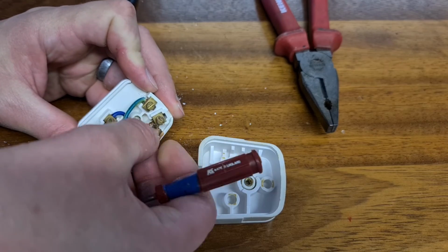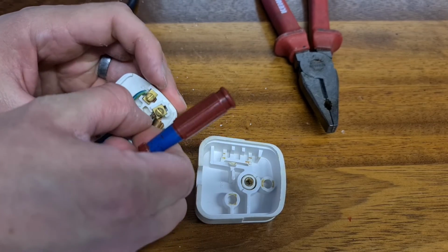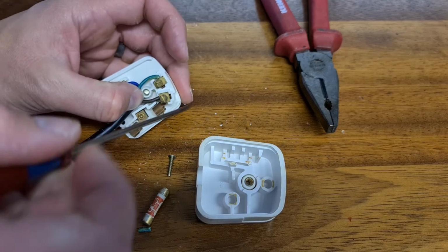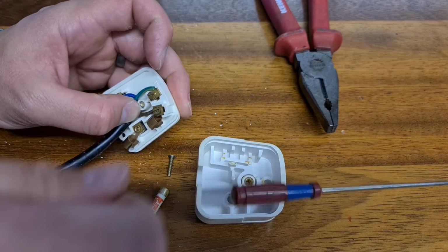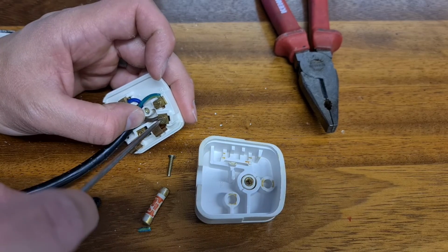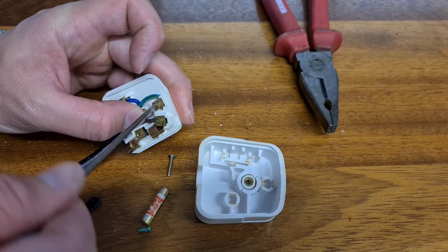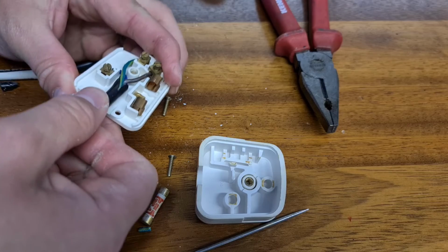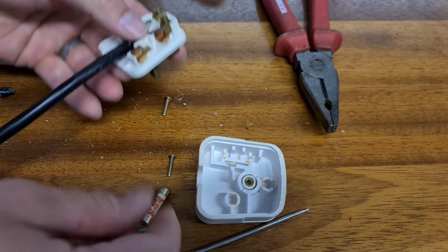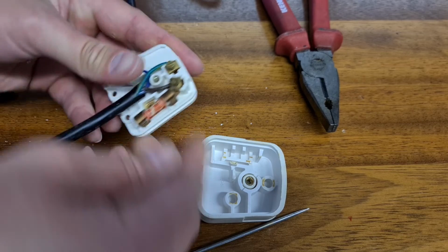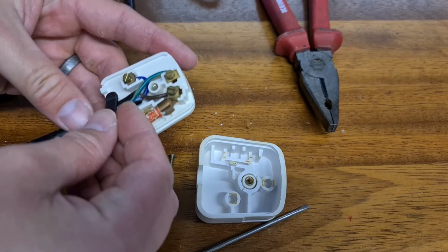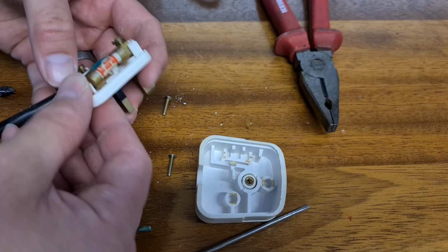Now the live wire is a bit tricky. We push it into there, and that is perfect. Screw it up, and we're good to go. All of these just need to be nipped up, and we should find with a pull it doesn't come out. We can put the fuse back in, it doesn't matter which direction we put it in. Then we put the cable tidy back on,